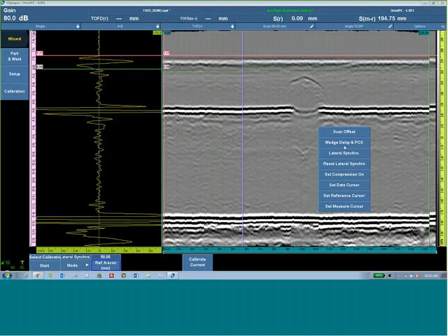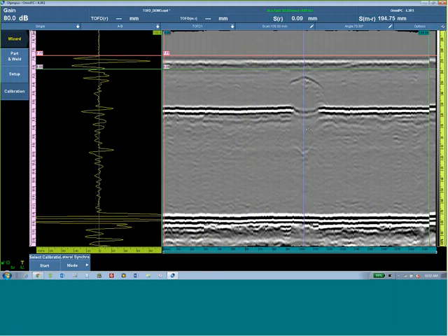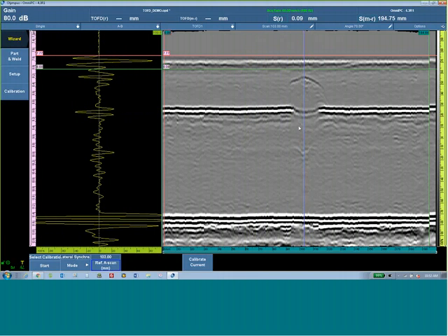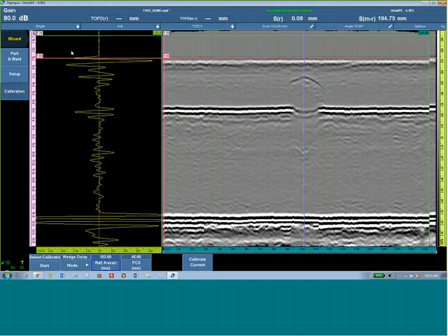So we're going to enter the OmniScan wizard, calibration. We're going to set a reference A scan that has a good lateral wave position, and in this case, we'll use the center of the flaw. We will select wedge delay only. In the wedge delay, we only require a single target, which is normally going to be the lateral wave, or a side drilled hole of known thickness if we can't see the lateral wave or back wall in a multi-group.